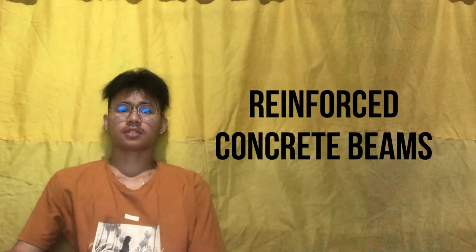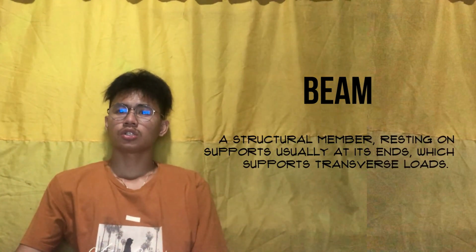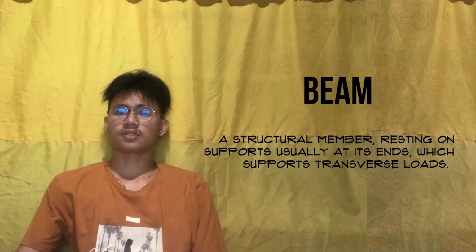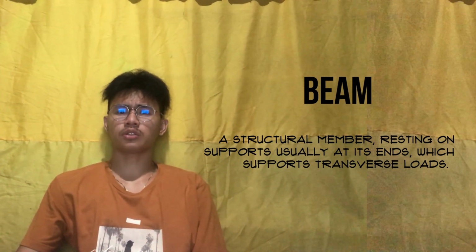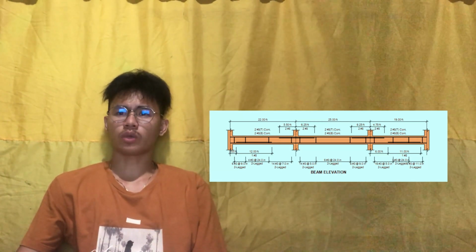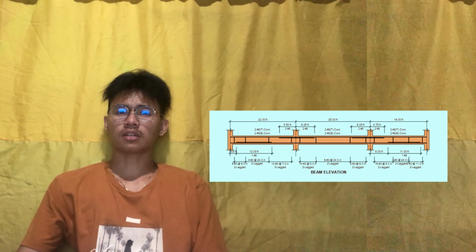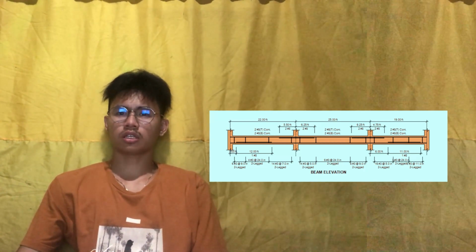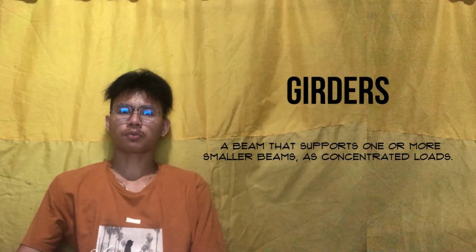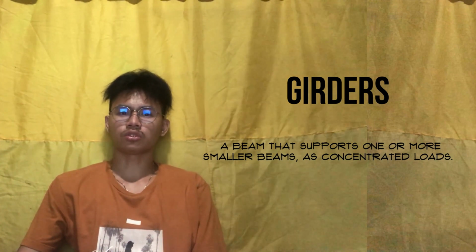Reinforced concrete beams. A beam may be defined as a structural member resting on a support, usually at its ends, which supports transverse loads. The loads that act on the beam, as well as the weight of the beam itself, tend to bend rather than lengthen or shorten it. A girder is a term applied to a beam that supports one or more smaller beams as concentrated loads.